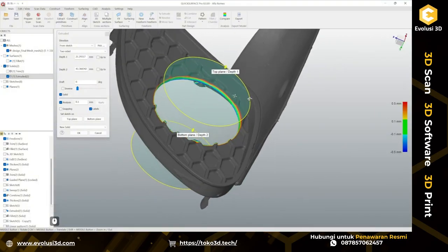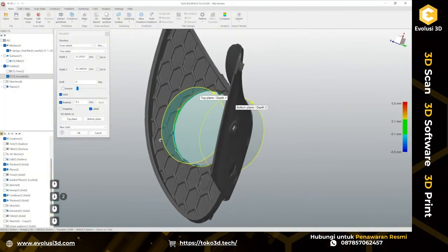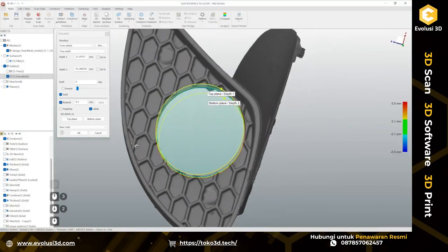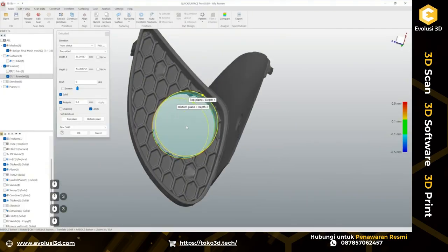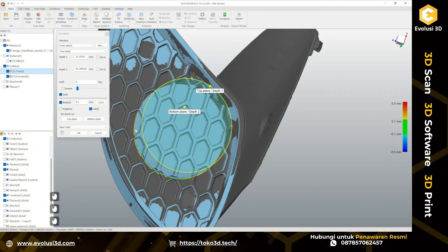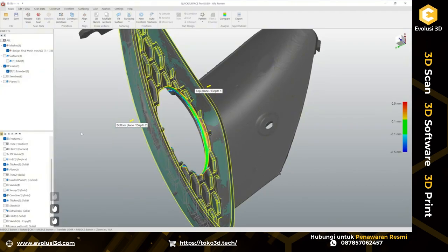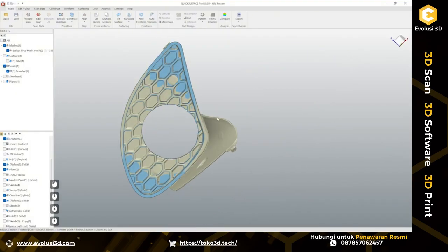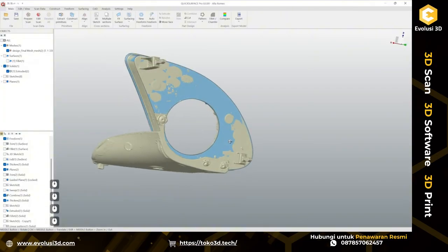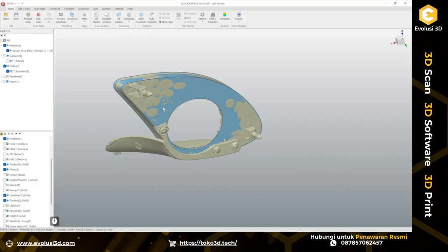Here we can see the deviation analysis. So again, probably the extrusion direction should be slightly sideways, considering deviation tolerance on this side and this side. But for this purpose, I'm just going to leave it as it is. I'm going to unhide my solid and say I want to cut it with the extruded solid. Okay, like this. So we have done most of the main part of this assembly here, and the last two tabs I still have to recreate here.